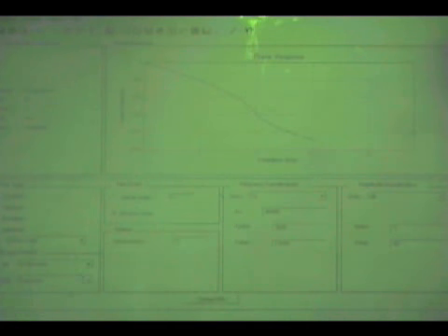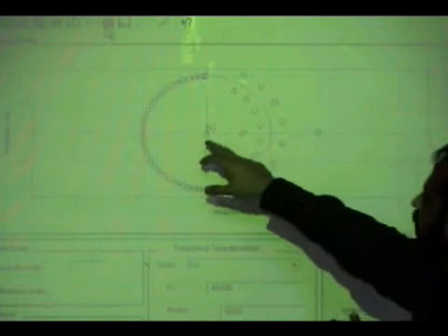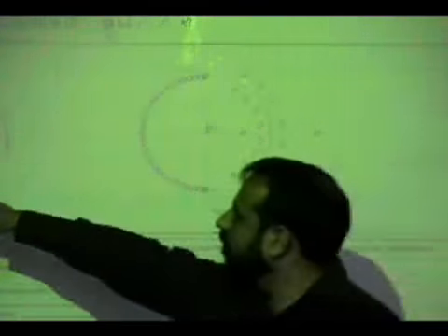Now you can design an FIR filter. In an FIR filter, what do you expect? Any poles? All zeros. In an FIR filter, there is no pole because there is no denominator. It says 50 poles at 0. That means it's z^-1, z^-2, z^-3. Order is 50, meaning 50 zeros in the system. It's an FIR system.